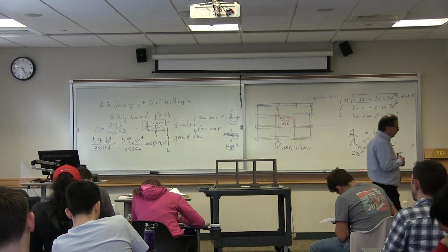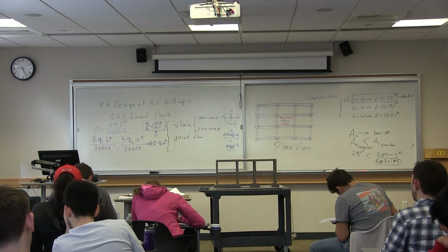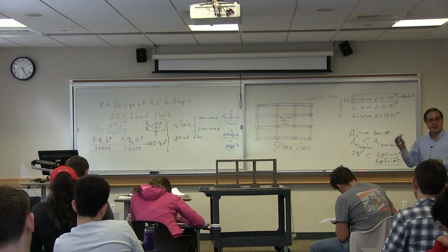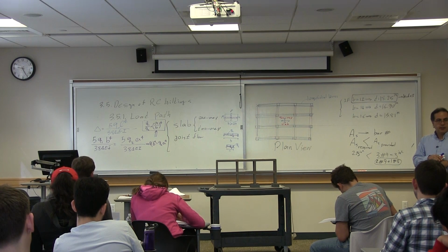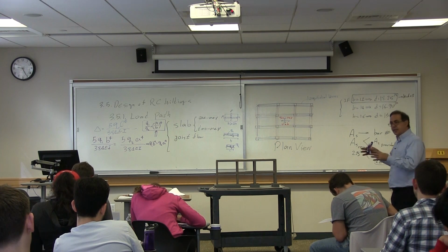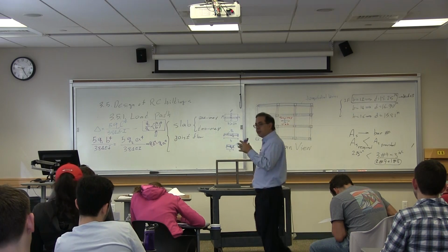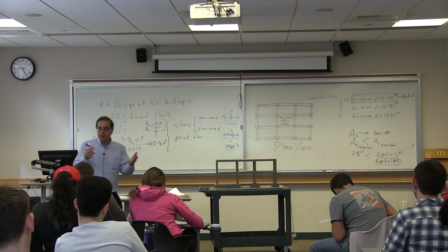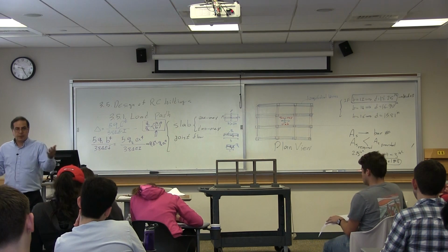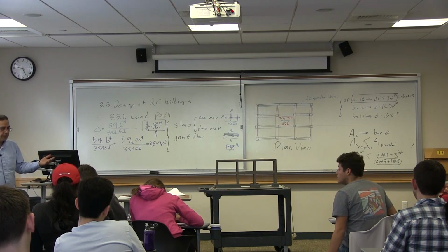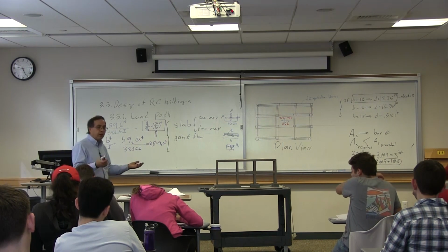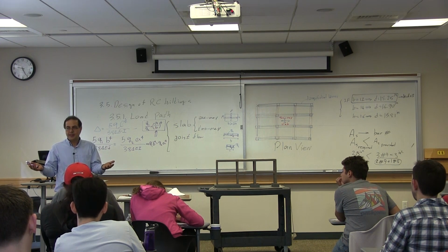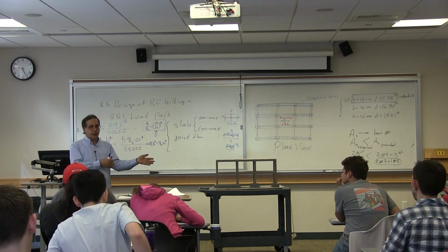In fact, what I want to argue and encourage you to do when you do your capstone, one of the first things you want to design is the floor system. Because if you change the floor system, the way loads are transferred will be different. If the loads are transferred differently, all the elements should be designed differently. Sometimes I see some students who do capstone, the last week they come to me, let's say, I want to choose my floor system. My answer to them is, it's too late. Because you have to change everything that you did.